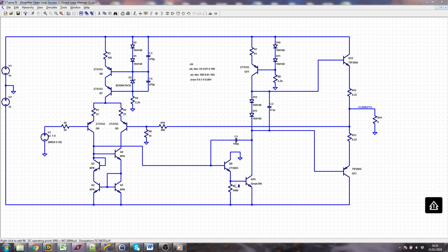Because the current flowing is so enormous, if there's nothing to stop it, or in this case it's switched on and it's taking 26 milliamps, but from this source only 11, so the rest probably from here, right? 15 plus 11 is 26, 26 in there, yeah, fits. This one, nothing doing, switched off, no surprise. This one's turned on, yanking this voltage down to the ground, down to the minus rail.